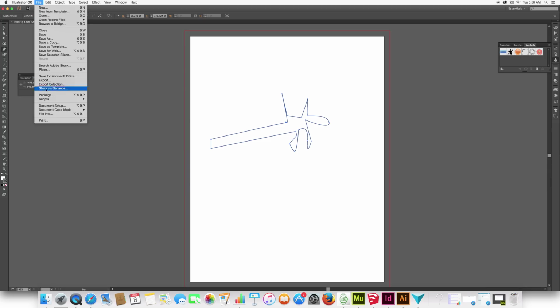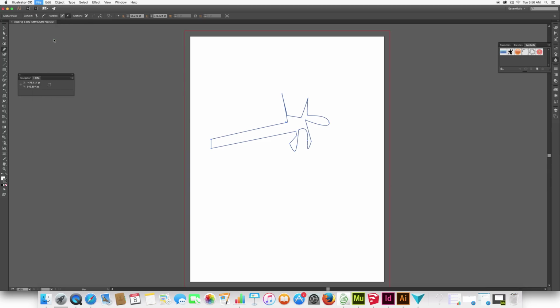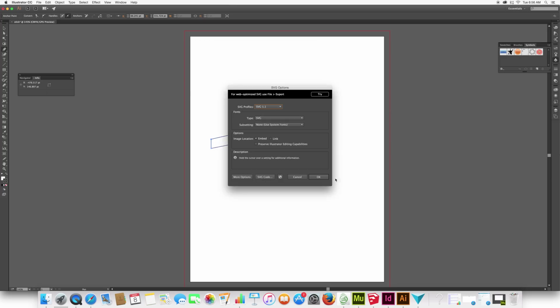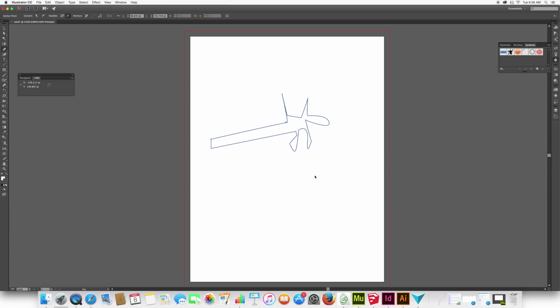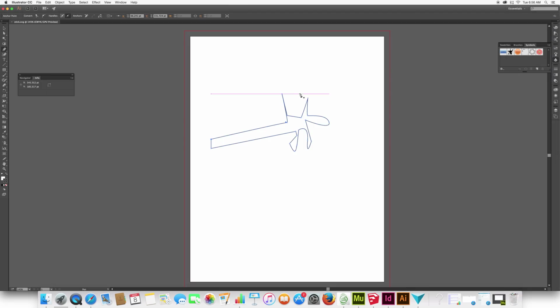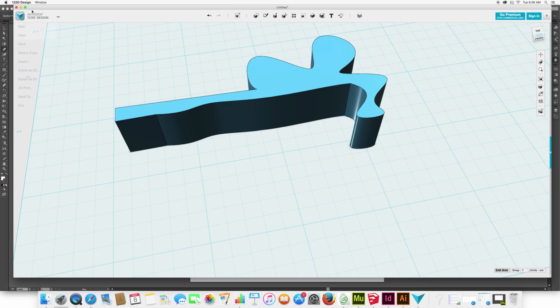You're going to save as an SVG. The SVG file is really cool because it can be read by 123D. So maybe you're better at using the pen tool in Illustrator. You're going to spend more than 2 seconds creating your model. But here I can actually import in my sketch. Solid chooses a size for you. I don't recommend that. Bring it in as a sketch.